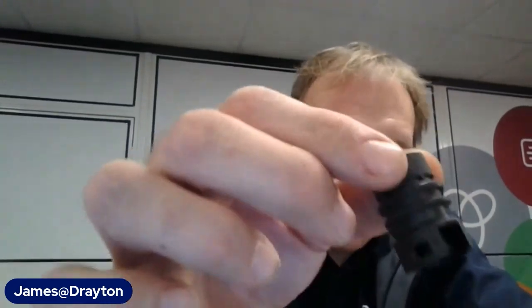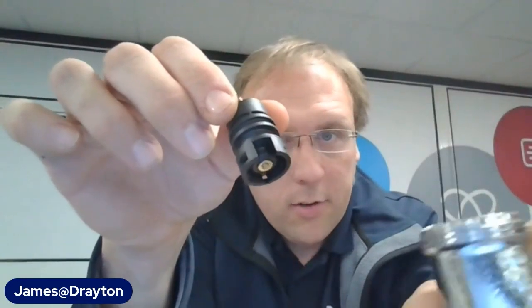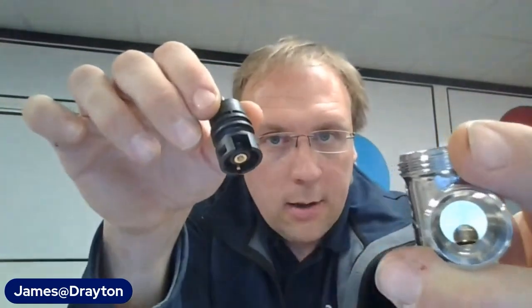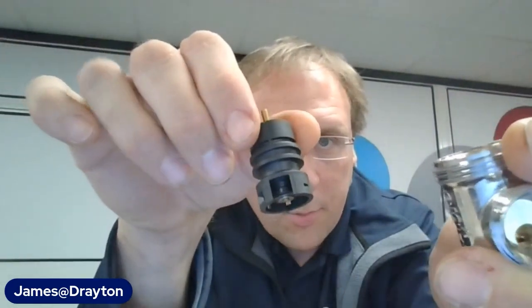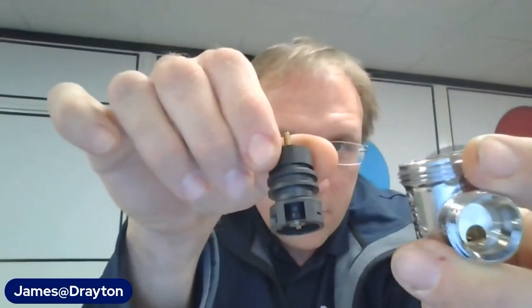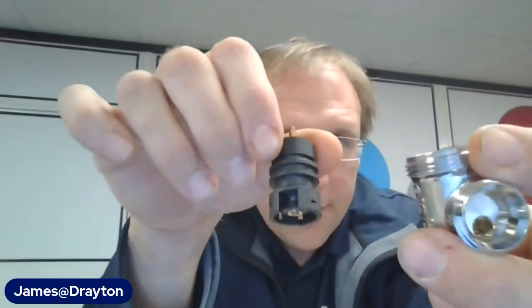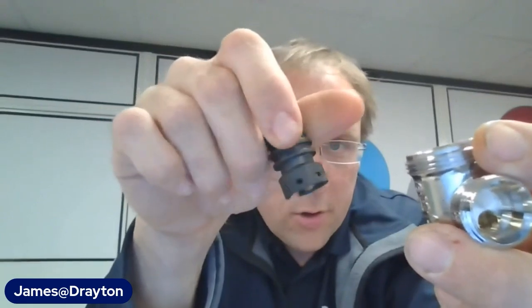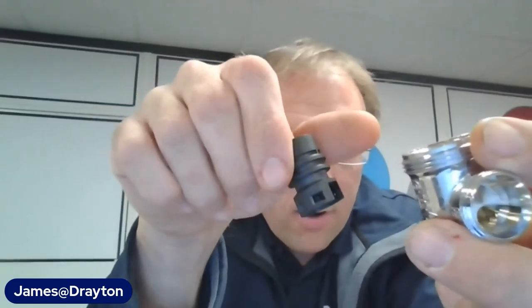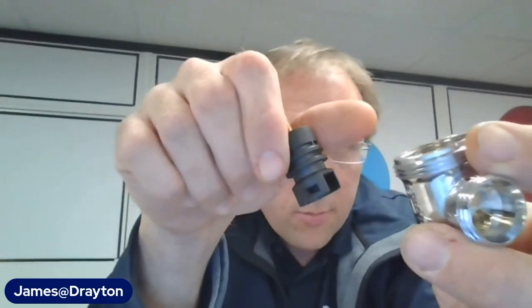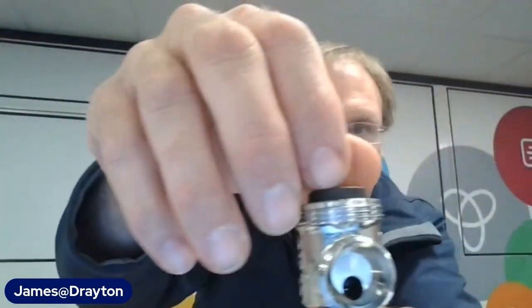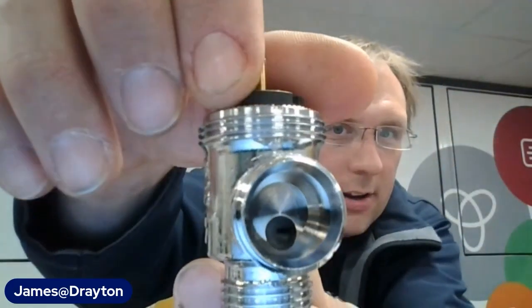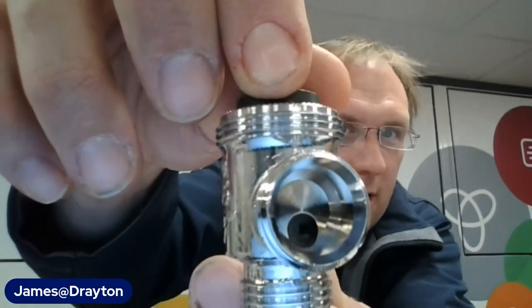So with the EB body, now I've just disassembled this one. So this is the insert that goes into the EB body. So there's your output port. And what happens is you align that with the segments around the bottom. So the big square there, the one I'm showing now, that's position 6. So that's essentially the body wide open. And then you've got positions 1, 2, 3, 4, 5, progressively getting bigger around the bottom of that insert. So when that insert sits inside, you can see, as I turn it, that we've got different size apertures.